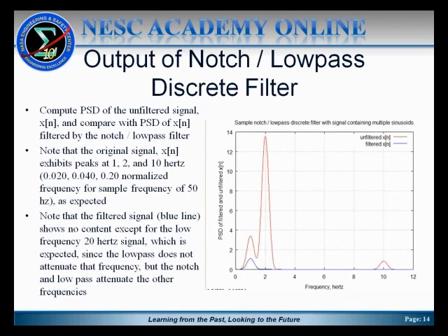You can actually use them to investigate where frequencies might be embedded in a signal, as well as get some insight as to what the relative magnitude of each of those components is. That can be useful if you're taking lab data for some device, be it a sensor or whatever, and you want to build a notch or low-pass filter to attenuate signals at certain frequency regimes that are not desirable in your flight controller.